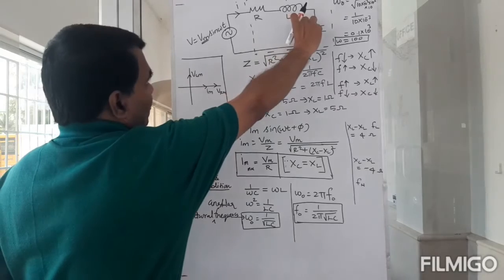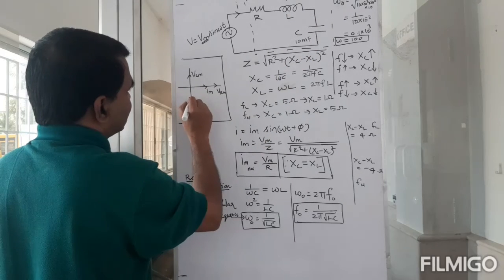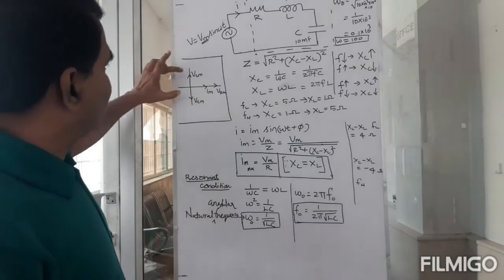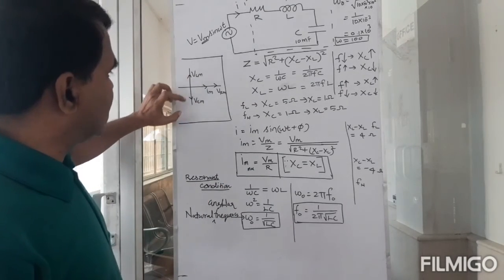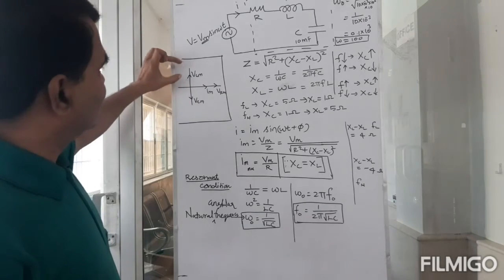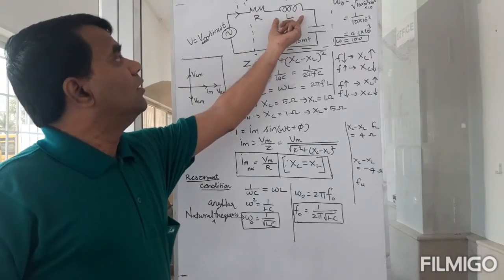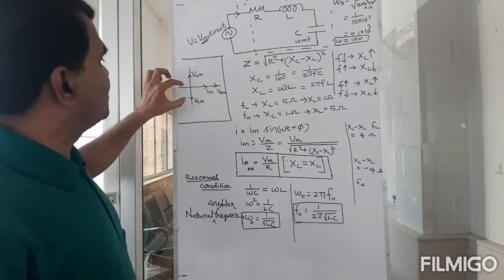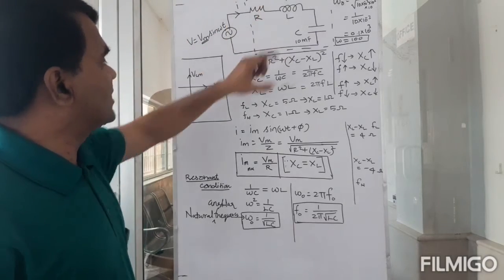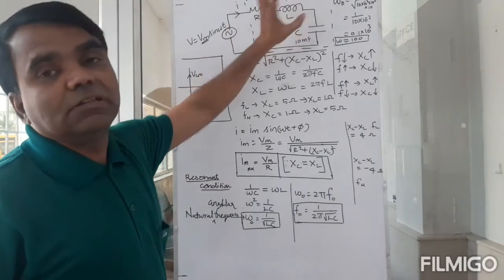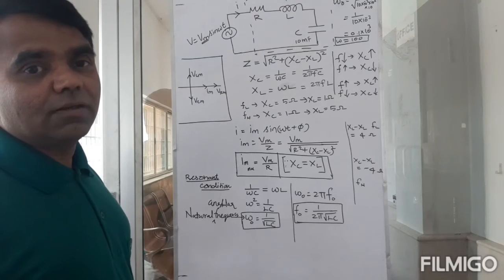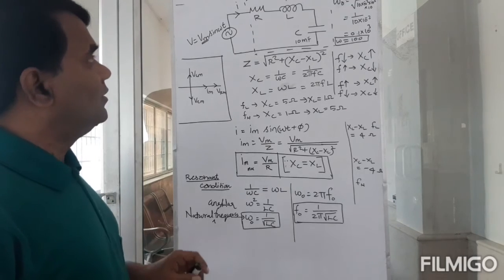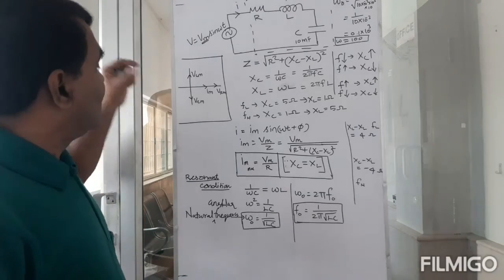And what about this voltage? That should lag the current. So notice here, this should be VCm. Note that VLm is always opposing VCm. So the voltage across the inductor will always have the opposite sign to the voltage across the capacitor. I want you to understand that.